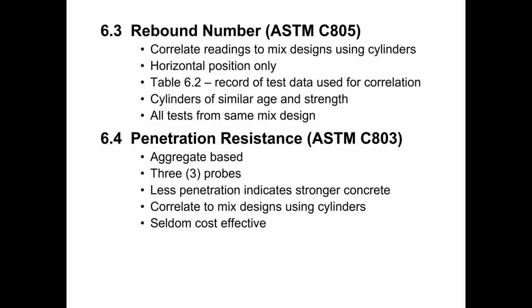So if we do this over a period of time for a range of concrete strengths, then we can use that data to develop a correlation curve. And so we'll talk in detail about how we go about developing a correlation curve in just a few minutes as we get a little bit further along into the chapter. All right, but the key thing to keep in mind here is that we have to go through this process for every mix design that the rebound hammer is going to be used.